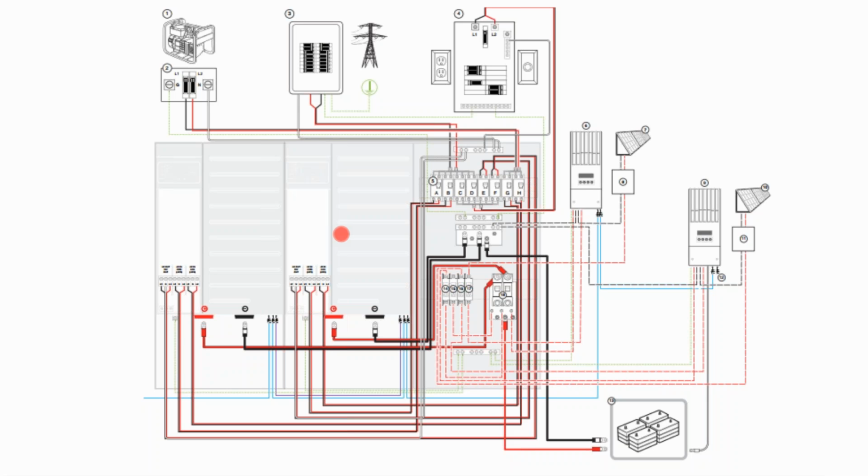That's a common installation error that I see in battery-based systems: they go and buy a 2 kilowatt battery inverter and a 15 kilowatt generator.